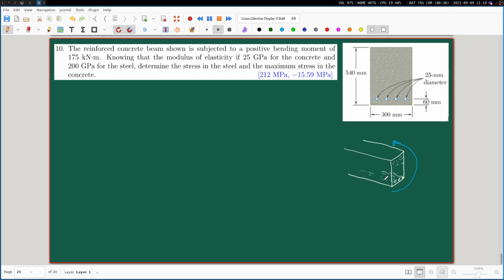It will contribute a little bit, but they say that as if it is not contributing. So if a design is made in such a fashion, then it is guaranteed to be safe, because whatever little contribution from the concrete there will be, it is only going to help the design. So the trick is like this, that if we consider this entire thing, suppose this is our entire beam where you have the steel rods present like this, you transform this thing to this kind of a cross section.